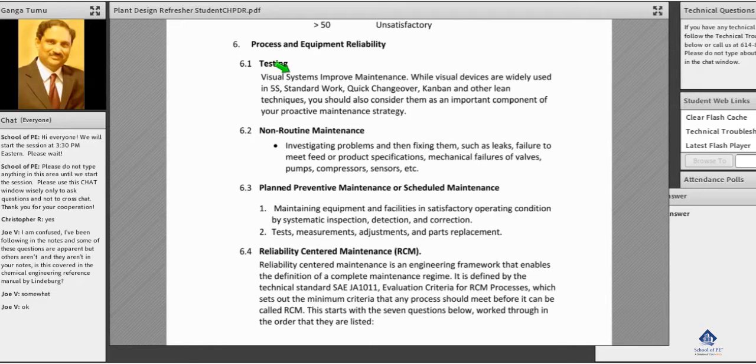The maintenance people going around on the floor see any kind of corrosion, erosion, and any abnormal sounds from the motors, gears, and pumps. Also, visually, they see any device with a problem, any leaking pipes, motor oil leaking, or the gearbox and other things.